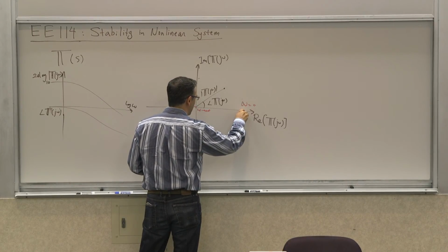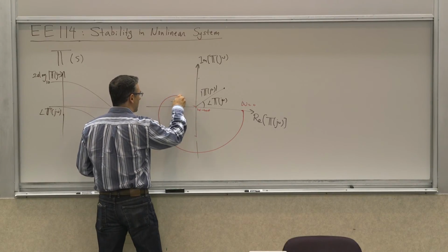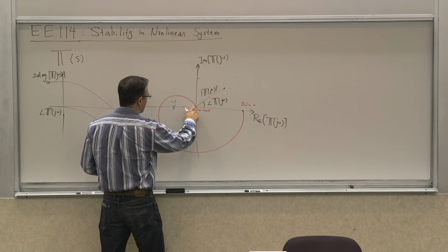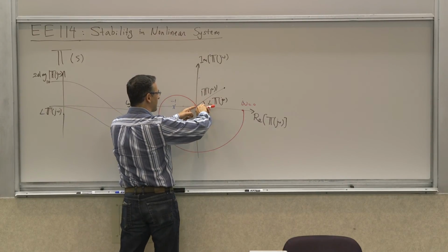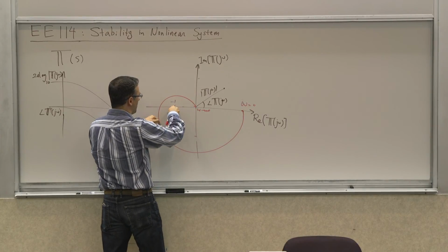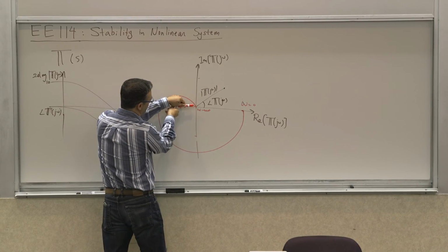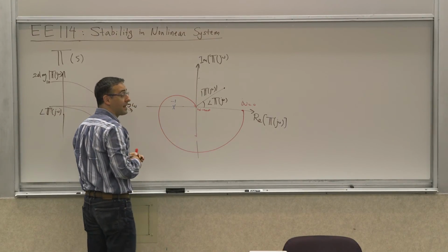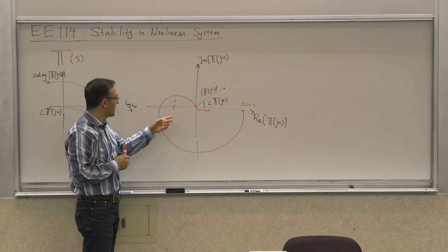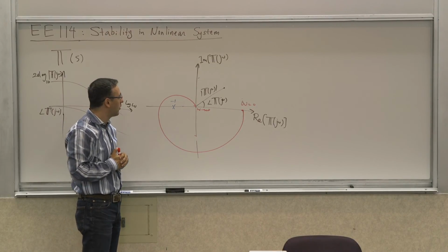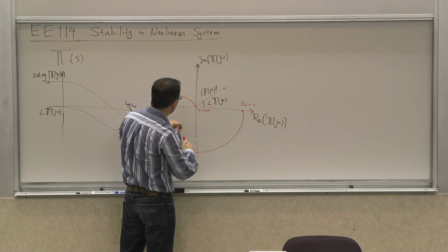So let's take a similar system, but it has a little bit more gain, and it essentially goes around it. So if you see, if I start from omega 0, I go up, I go up, and I go up. And this is the first half, and the second half would be the mirror image of that. It would produce a full encirclement of this thing. So this is basically one encirclement. This would produce one right half plane pole. So you can see that we have it.